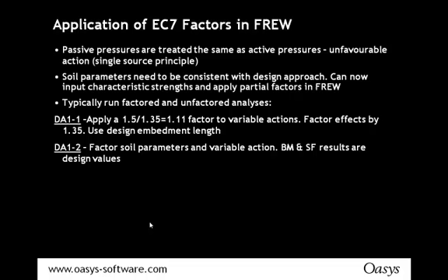Within the United Kingdom, if you were using design approach 1 and designing a retaining wall, you would probably start with design approach 1, combination 2. That's because this affects the stability of the wall, and it also gives the design values for bending moment and shear force. And then with design approach 1, as well as applying the factors on your actions, you would also apply the material factors on your soil properties. But it is important and critical to look at design approach 1, combination 1, and the reason for this is because it might be critical for structural effects.